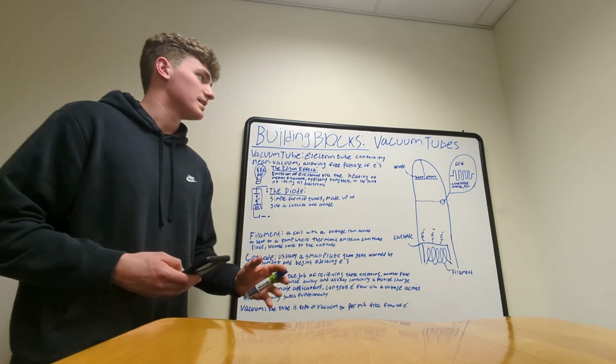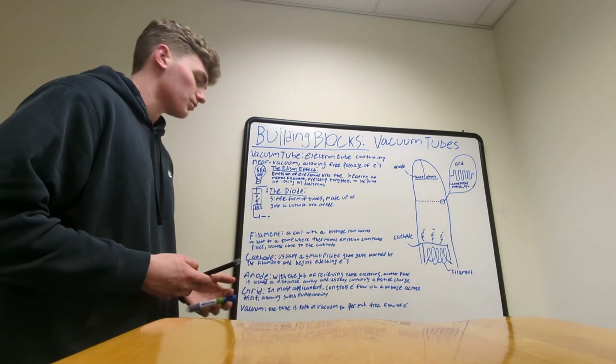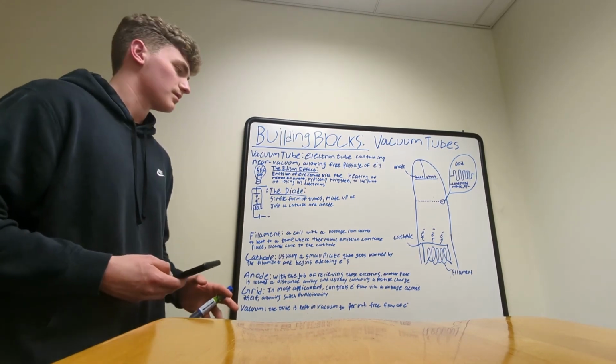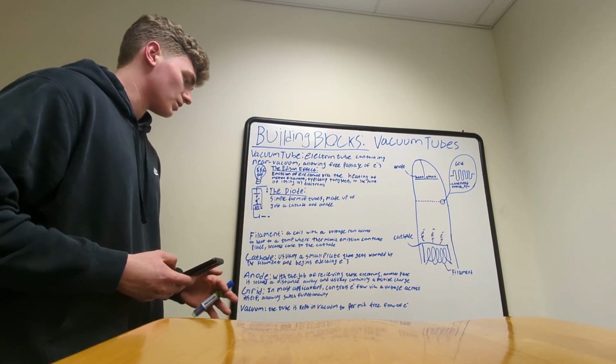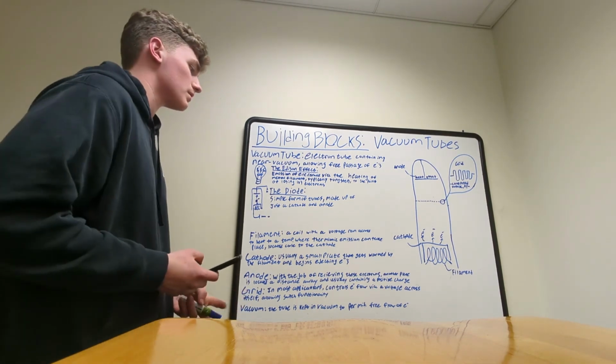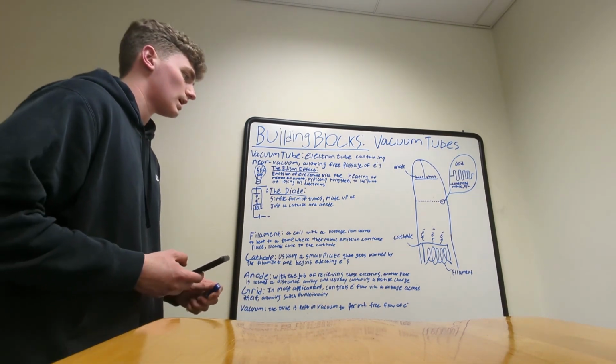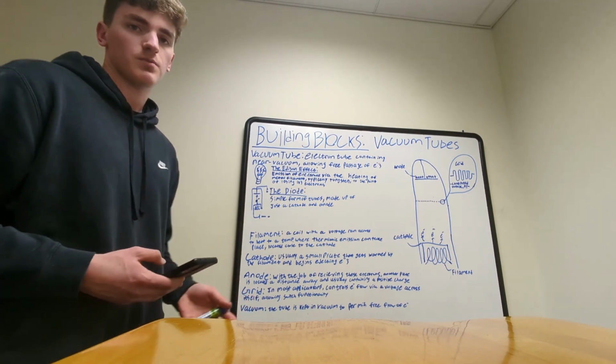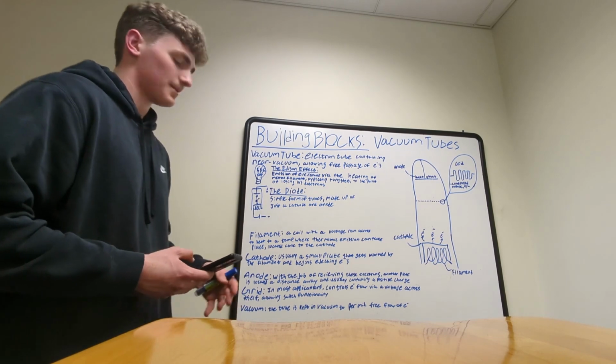Another important piece that is in the most common form of these vacuum tubes is called the grid. This is what gives us a lot of control. In most applications, it's able to control the electron flow via a voltage across itself, which allows for the switch functionality that I was talking about earlier, a switch with no mechanical analog. And then last but not least, the vacuum in the tube is necessary to permit the free flow of electrons, with nothing getting in the way.